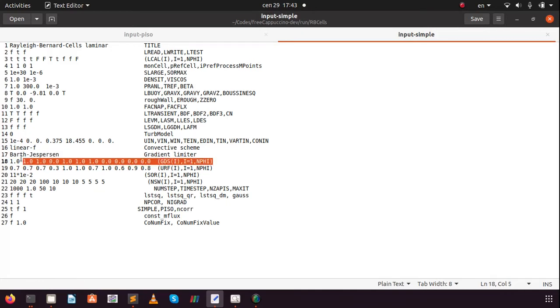For these gamma coefficients, they are all 1. These are used in, let me recall, deferred correction. Yes, we'll discuss that more in detail when we go through the code and theory. Under-relaxation factors are familiar values of 0.7 for velocity, 0.3 for pressure, and 0.7 for temperature.